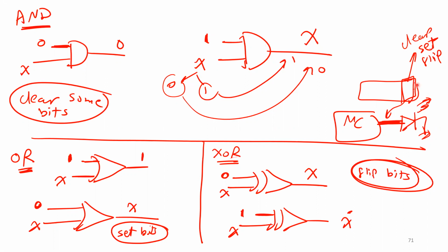Okay, guys? I give you here again examples, the same example here. As you will see in the next chapter, you have here 8 pins, external pins. Every pin is connected to one bit in a byte in a port. So in programming, you have to read this byte. After you read this byte, if I want to put 0 volt here to turn the LED off, all you have to do is put 0 in the corresponding bit, because every pin has a corresponding bit.